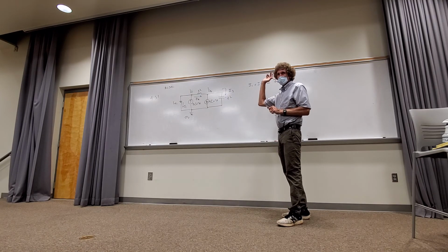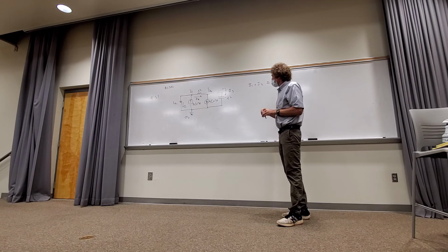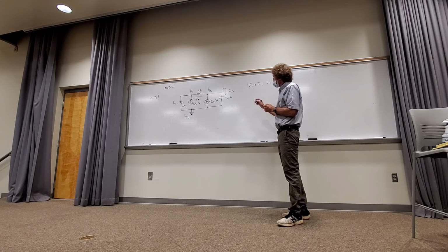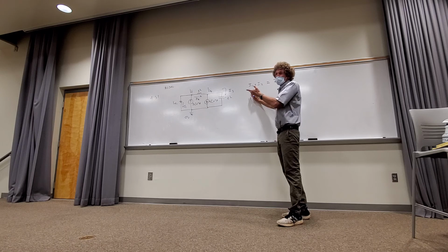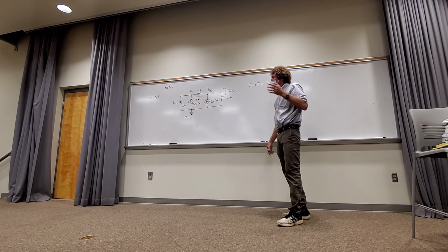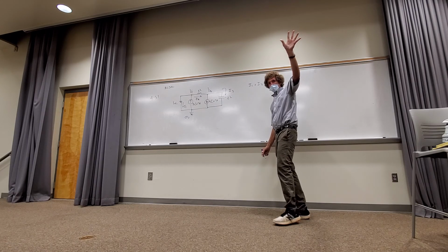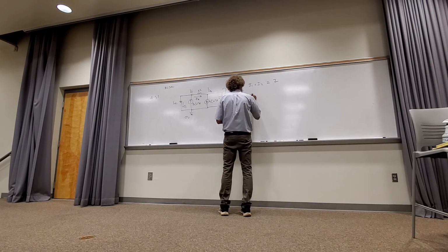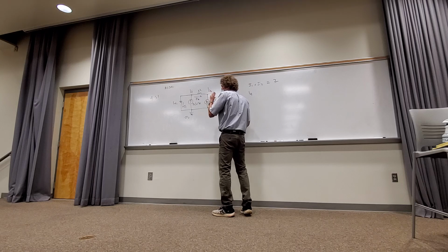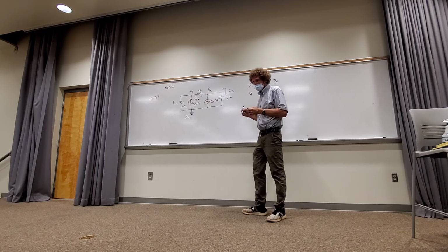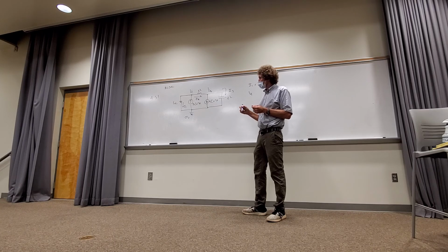Show of hands here if you do. All right, now I have to replace the currents with the voltages, right? So what is I1 in terms of the unknown voltage for the voltage node? Class? How many see it's V1 over 1? Right? Sure. So I1 is just V1 over 1. Why write a 1 down when you don't have to? Just V1 over 1 or V1. Do you agree with that? The units would be ohms.